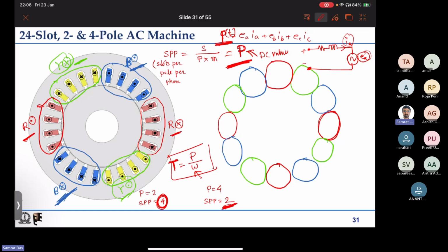We can have a steady DC torque without any ripple, ideally. That is the advantage of injecting sinusoids, because theoretically it is possible to have constant power in time, and it is possible to have a DC torque value without any ripple.